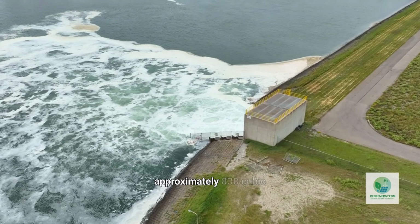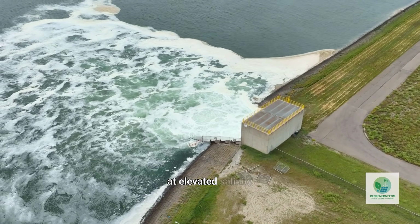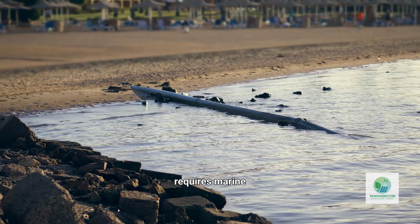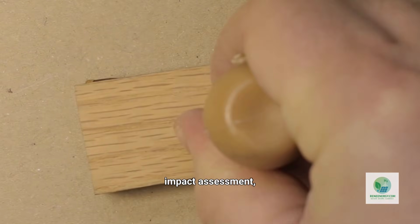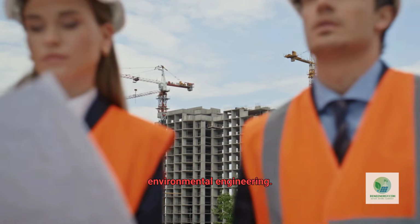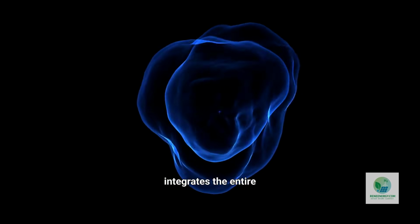Brine discharge equals approximately 838 cubic meters per day at elevated salinity levels of 65 to 70 grams per liter. This requires marine diffusers, environmental impact assessment, and regulatory approval. Water sourcing becomes environmental engineering. Finally, move to image number 9, which integrates the entire energy flow.